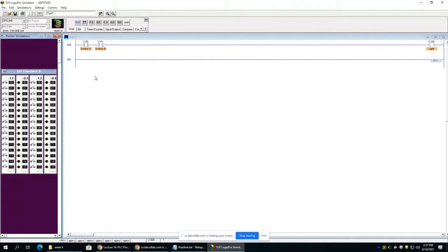You'll program it, and then you have to move the program from the programming device to the actual PLC. And once you move the program to the PLC, you can actually unplug the programming device if you want to. That's called downloading the program.